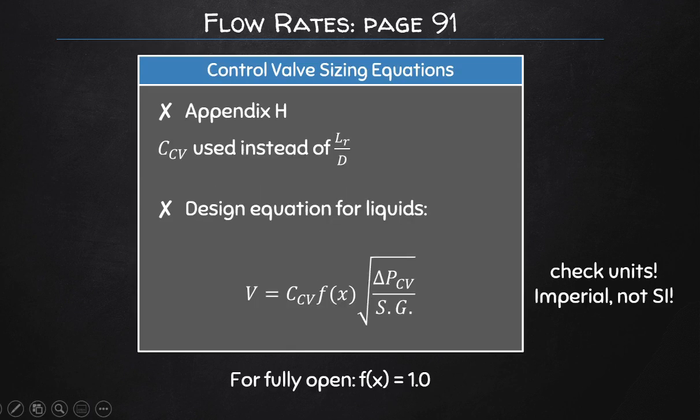In the design of control valves, two approaches are typically taken, and these are based on handling non-flashing liquids or gases and vapors. So depending on whether you have a liquid or a gas or vapor, you would go with a different approach.